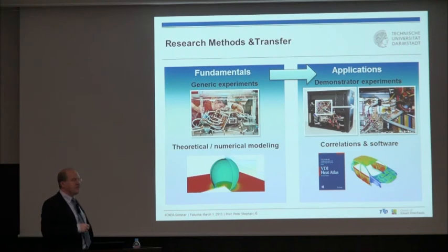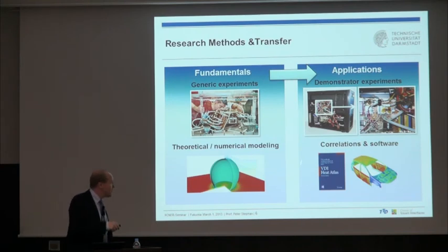For example, we developed a quite nice, in such a generic experiment, we found out that we can have a porous structure where we have evaporation of methanol from this porous structure with very high heat flux, and we implemented this to cool a PC. We took out the standard cooling of a PC. We placed our own cooling with a capillary-driven system, and this works fine, and this is a kind of industrial demonstrator. And we always try to find some correlations here to put them into handbooks, preferably, because I'm the editor-in-chief, into the VDI Heat Atlas, and also we try to develop software.